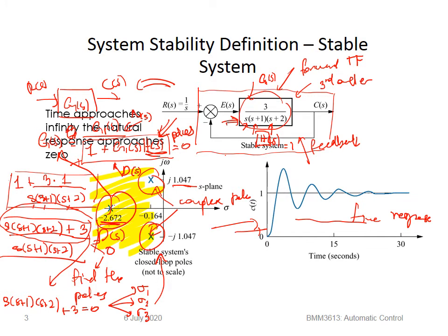So as time approaches infinity, I'm sorry, I have written in the text here that as time approaches infinity, the response approaches 0. Well, now it's not 0. There's a mistake here. The error approaches 0, but what happens here is that the response approaches a finite value, which is 1. So it is a stable system. We have a specific input 1 over s, and we have a finite output value equal to 1 after a certain undulation, right? So this system is stable.